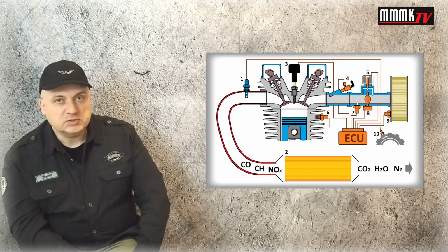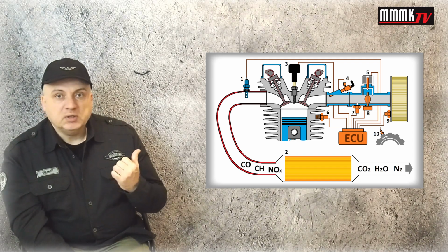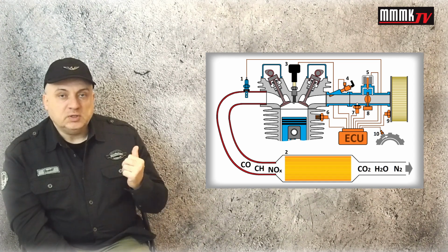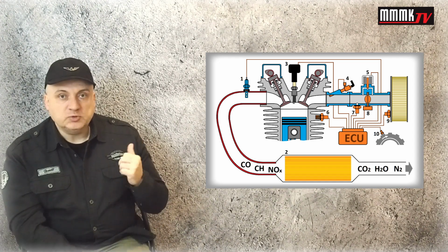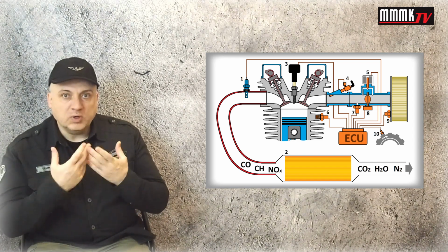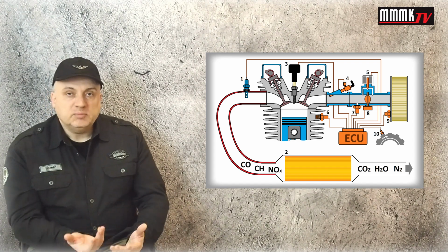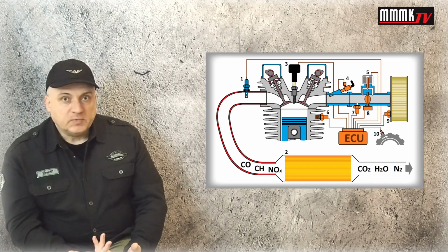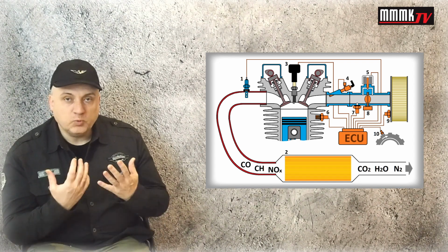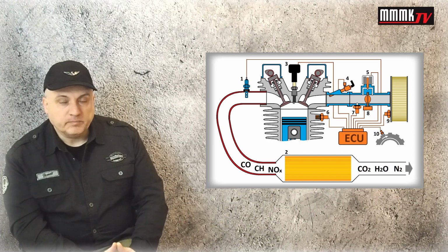Just simplifying the story, and this has to be processed very quickly. The ECU has to be able to change the injection dose from one working cycle to another, and sometimes it is like 50 working cycles per second. So it has to work really quickly.